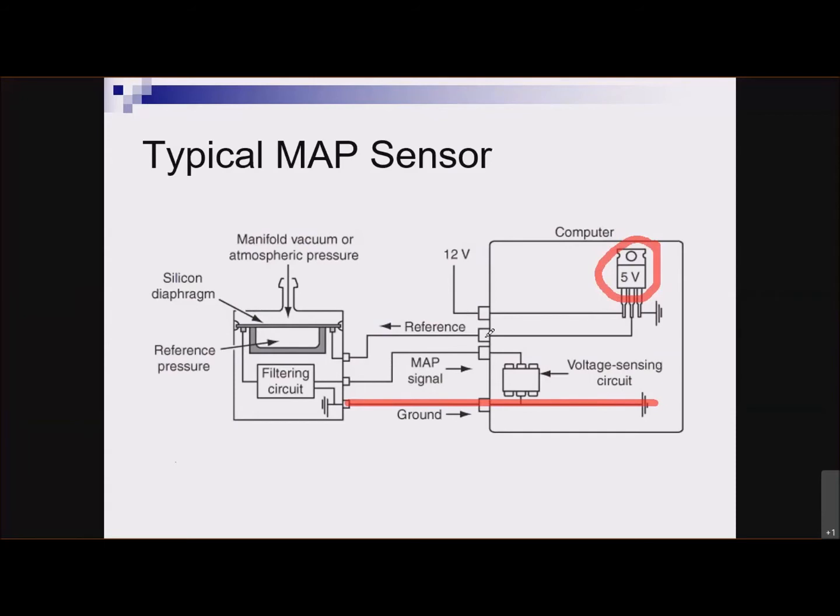So, 5 volts and ground. If you put a voltmeter across that wire and that wire, in my experience, you'll get almost exactly 5 volts, no matter what's going on in the car. So it might be 4.99, 5.02. It's usually within a couple hundredths of exactly 5 volts.